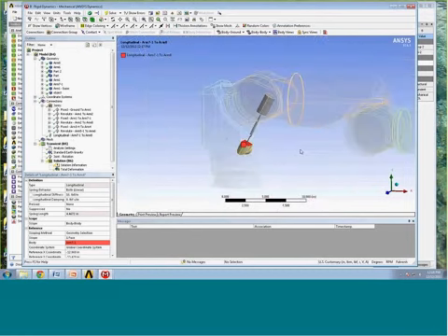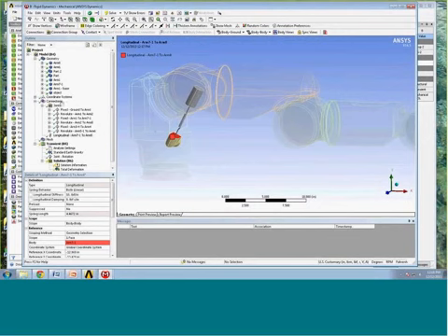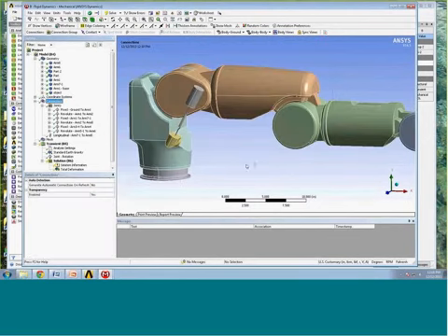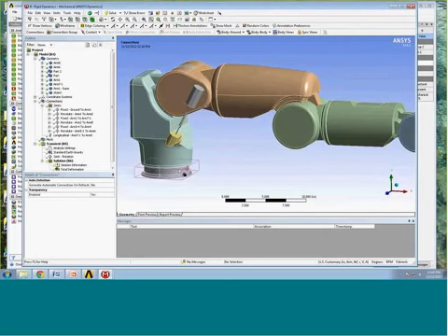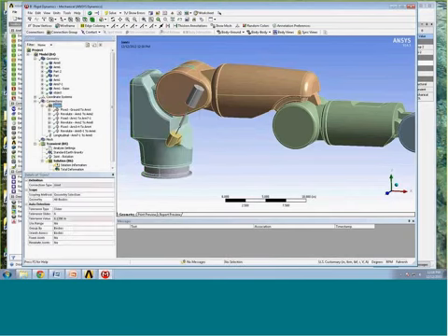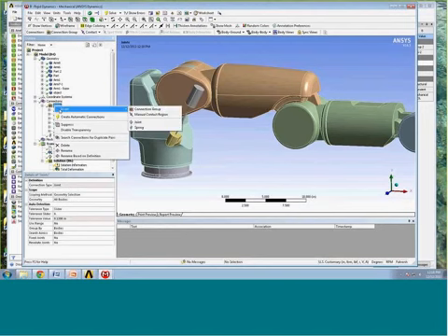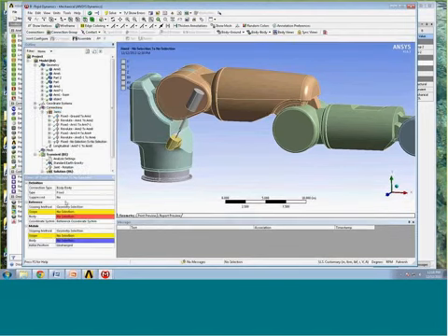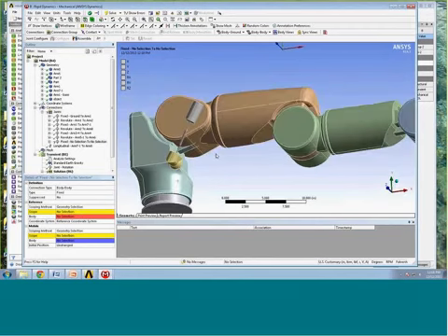Okay. Now I'm missing a couple of joints in here. I need to have a joint that I can use to define the rotation of this base arm, the 45-degree rotation. So I want a connection, a hinge connection, a revolute connection between this base and this first arm. So I click on joints, right-click, insert a new joint. I have to pick a reference side and a mobile side. Now for the revolute joints, it doesn't matter which one I choose as which.